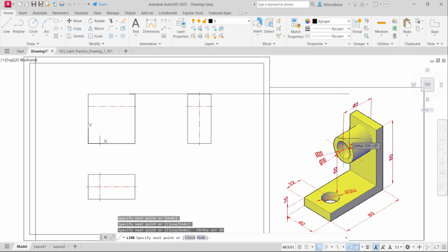Then I'll have to go down a bit. How much? Well, this is 30. The diameter of this big circle is 30, and I have it placed from the center to the top has 20. So that means that it must have like 5 millimeters here. So I'll go 5 towards the bottom.